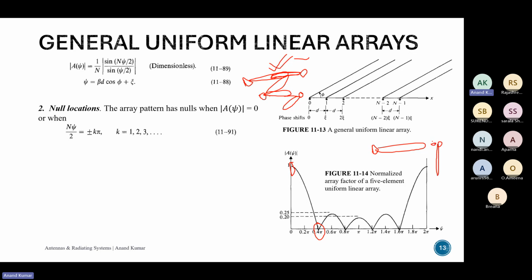So it will essentially mean the antenna has very poor gain in this direction, and its reception will be poor. So it will rely on the gain of the other antenna, which is trying to communicate with it. If the path loss is much greater, then you could lose all the signal strength. So it's very important that we know where the null is.